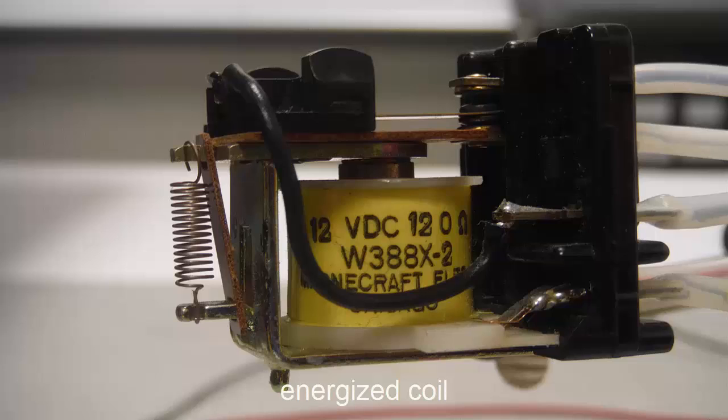When the coil is energized, it pulls the lever arm down and the common in the center is disconnected with the normally closed contact at the top and making contact with the normally open contact at the bottom. This is associated with a characteristic audible click that can be endearing or equally maddening depending upon the application. Solid-state relays, as we'll learn in later lectures, do not click because there's no moving parts to clack.